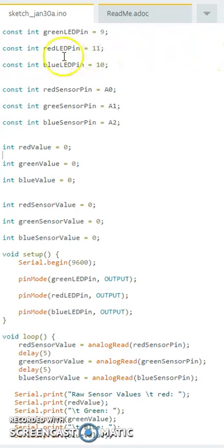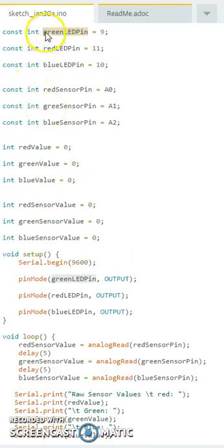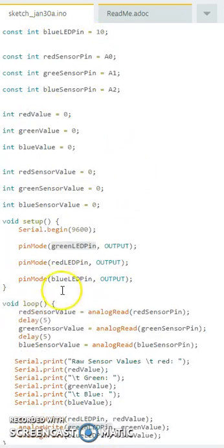First of all, with the basics of the Arduino, we're going to want to set up a constant integer, which causes port 9 on the Arduino to become this name. You could do this with anything, so you could set port 9 to whatever you want. As I highlight that, you see where it's used throughout the code. If you were to change the name of that, you'd have to change the name of all of these down here.